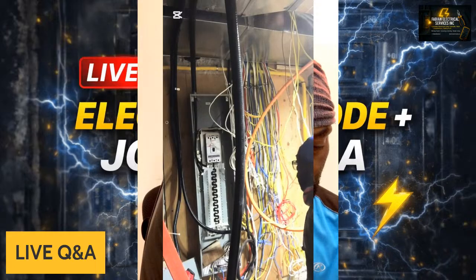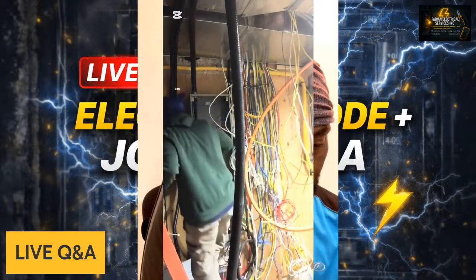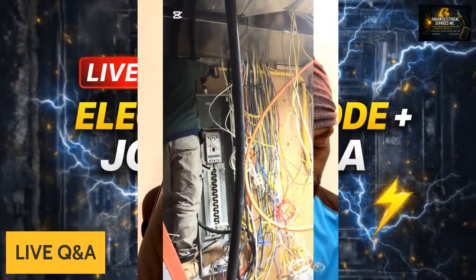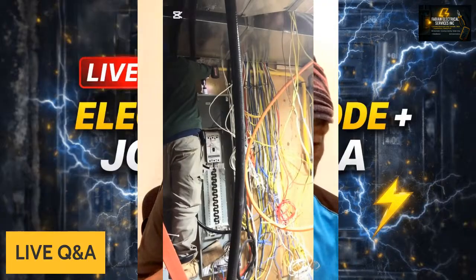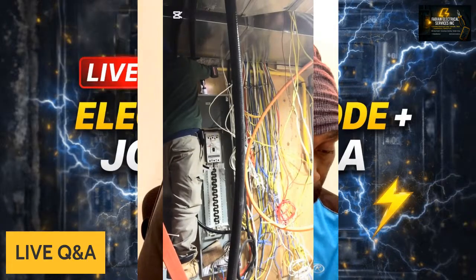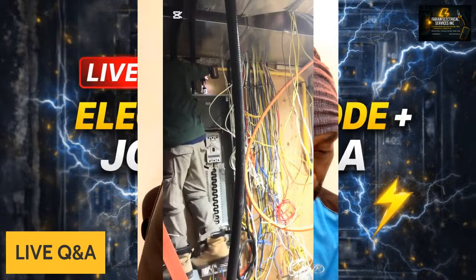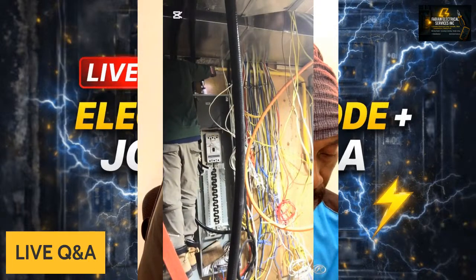So again, this is an installation of the 400 amp service that's being installed, using parallel feeds to power up this unit. 250 kcmil wire two times in order to have my 400 amp service. So again, what you will see me doing in this video is simply trying to install my cable into the panel.